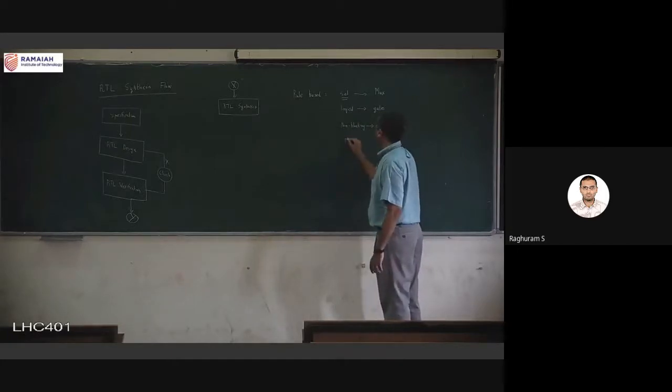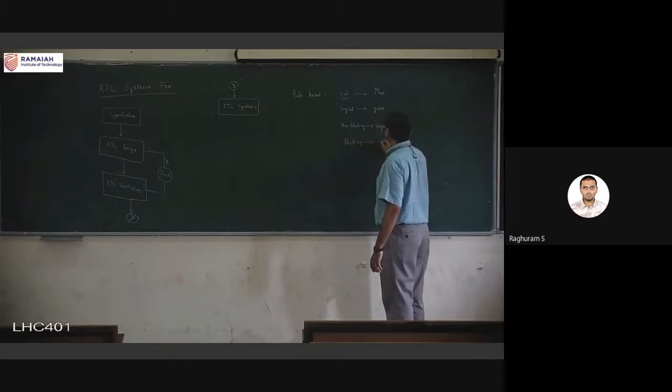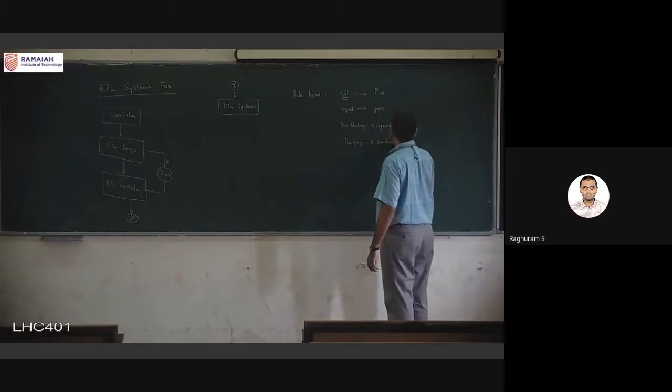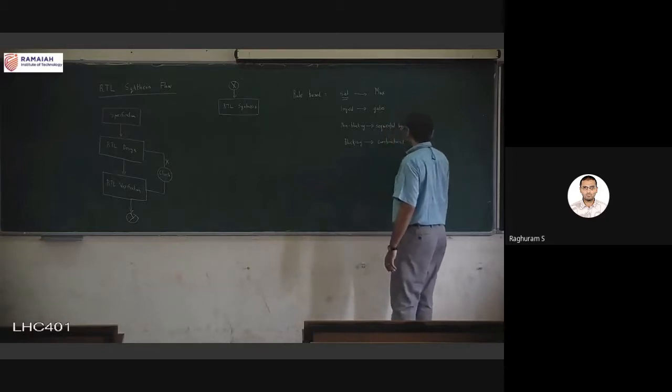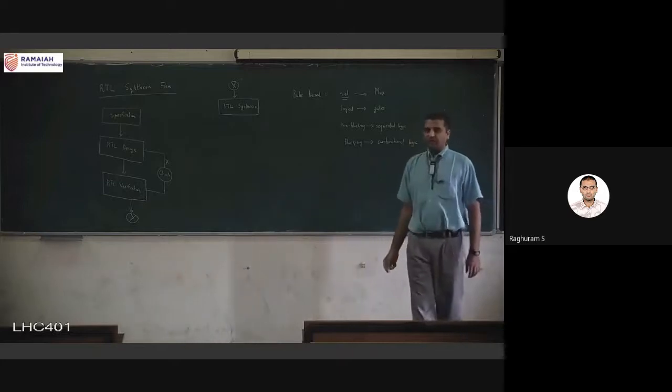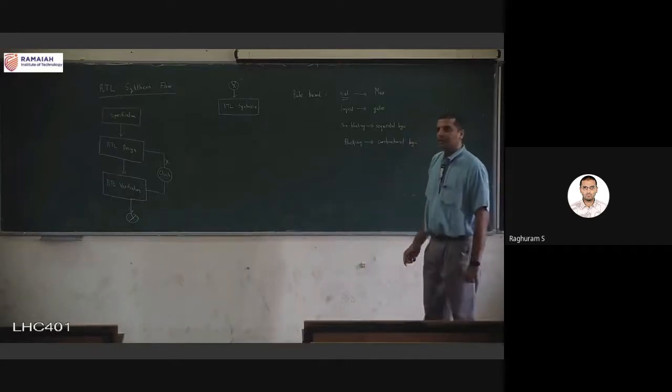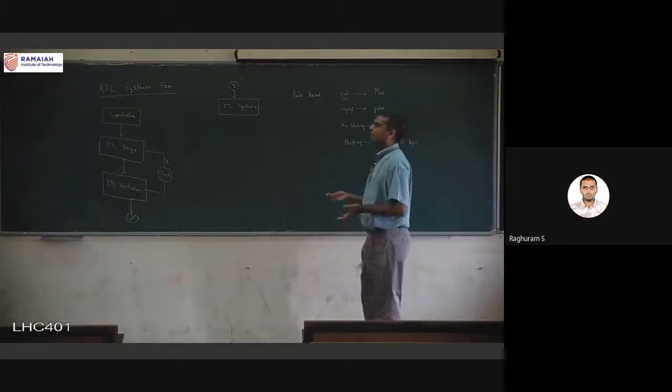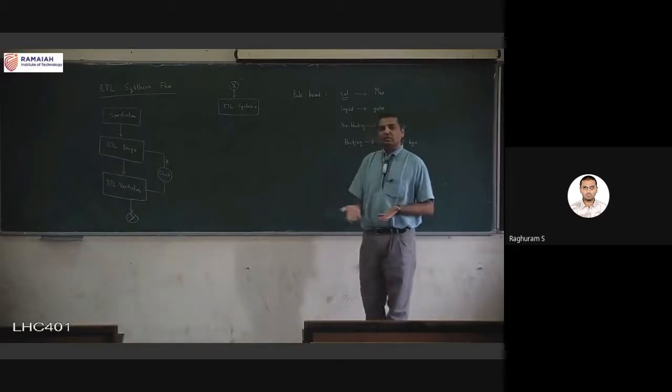These rules are more top level rather than directly translational. But when you have non-blocking statements in your design, generally that means that you are designing a sequential logic.